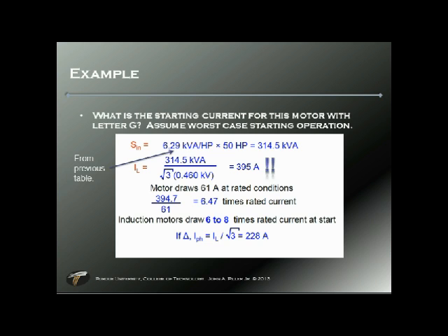Now what's locked rotor mean? Well, locked rotor is essentially your starting current. We all know that when you start a motor, it has an inrush current, we call that. Well, the technical term for that inrush current is locked rotor current when we're speaking about motors. Inrush current is what we talk about for inductors itself. Motors, we refer to it as locked rotor.